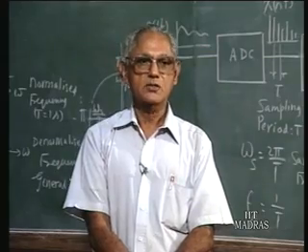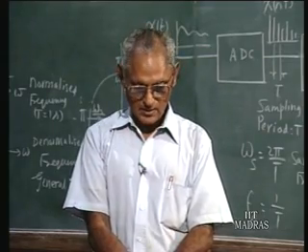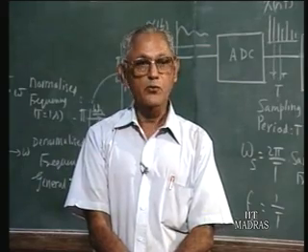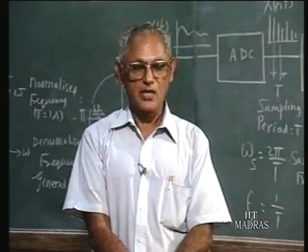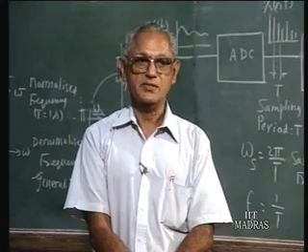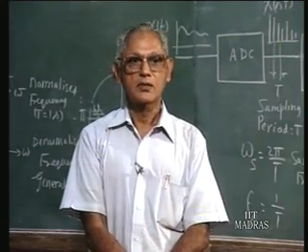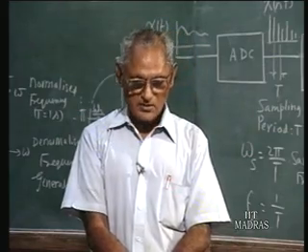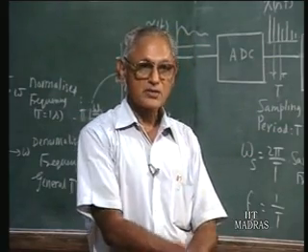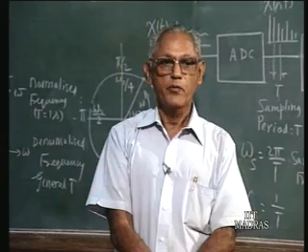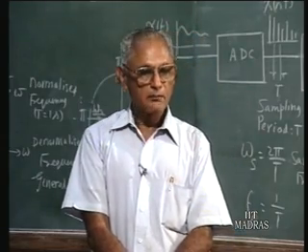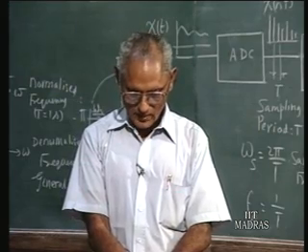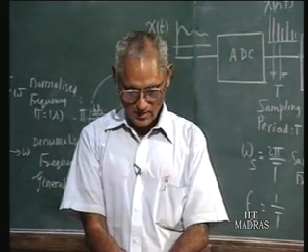What we have not done in this particular set of lectures is discuss the concepts similar to Fourier series and Fourier transforms in the continuous time case. Here also we have discrete Fourier series and discrete Fourier transforms. These follow analogous lines as the continuous time systems, and we can think of the discrete Fourier transform as a special case of the Z transform when z is e to the power of j omega, but that is outside the scope of our lectures, so we did not discuss that.